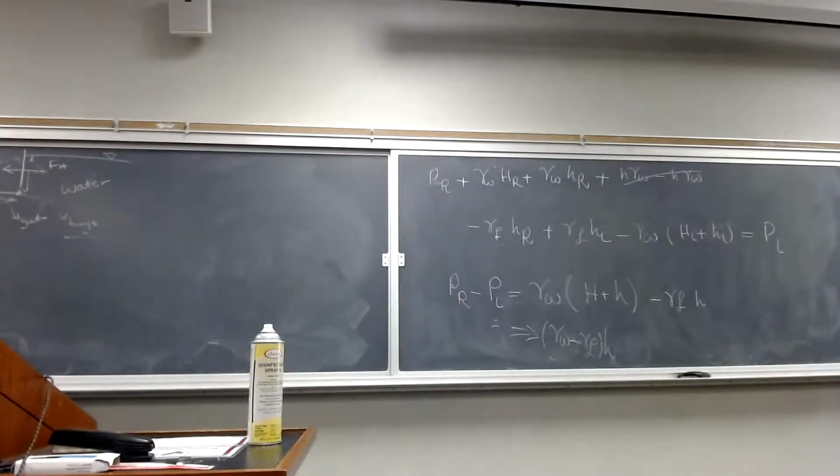And all of these are hydrostatic forces, so they are essentially a function of your depth, right? F of V can be calculated from the pressure distribution on the bottom. Since on this horizontal plate, the depth of the fluid doesn't change, your pressure is going to be uniform.